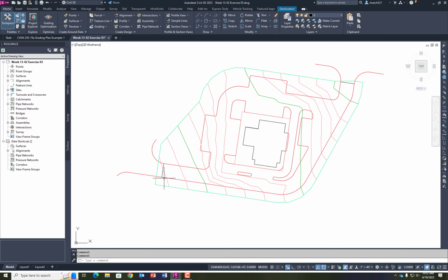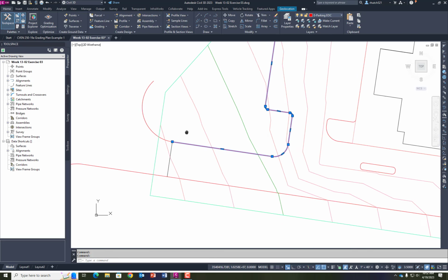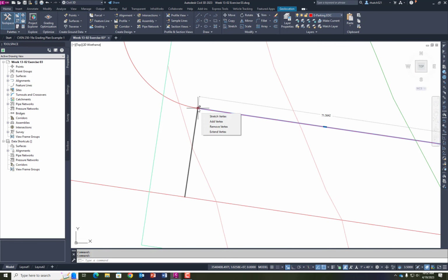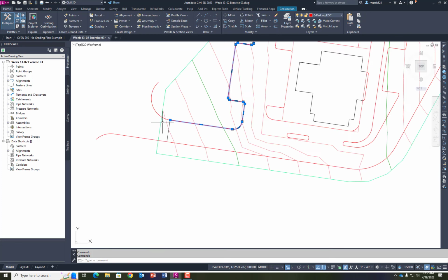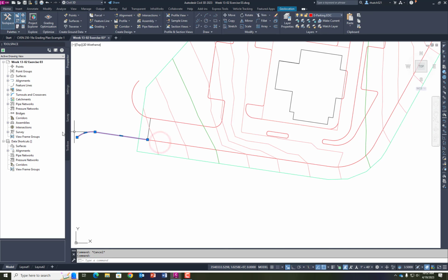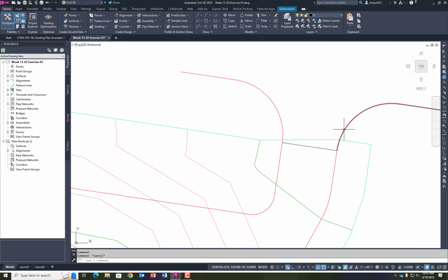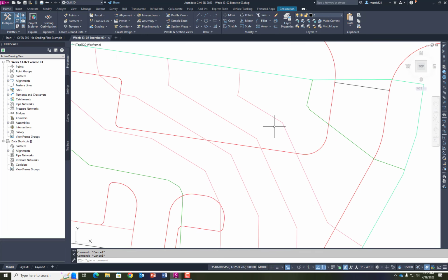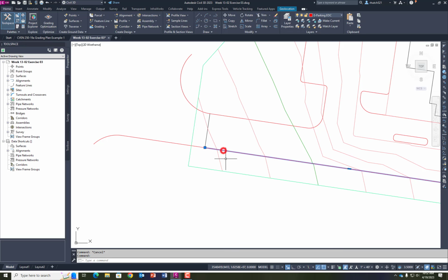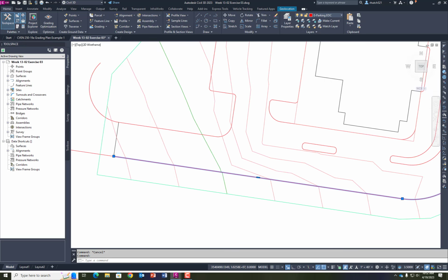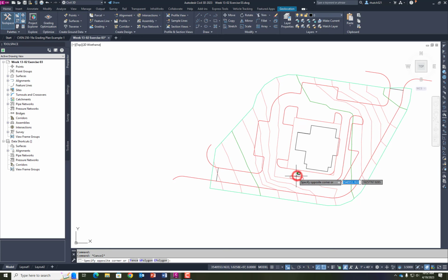What we're going to do is, if you look, I went ahead and cut mine off right here. I made sure that it cut off and didn't include that portion of my road. I did the same thing up here. It's cut off at that point. Now this is really important: you want to make sure you do this yourself on your design. So it's cut off, and then I came in and joined all these together. And this is the other imperative thing. These have got to be joined together. Otherwise, you are going to have the biggest headache trying to make these corridors.